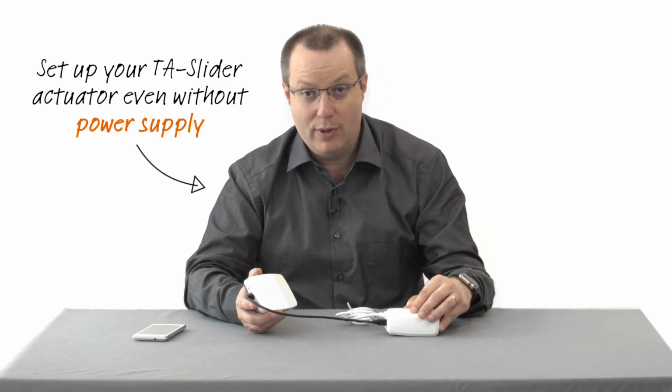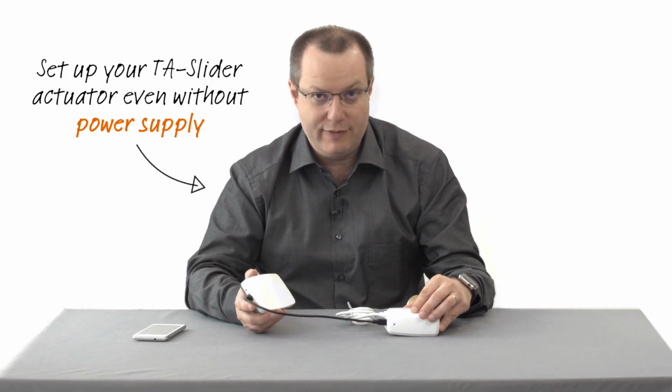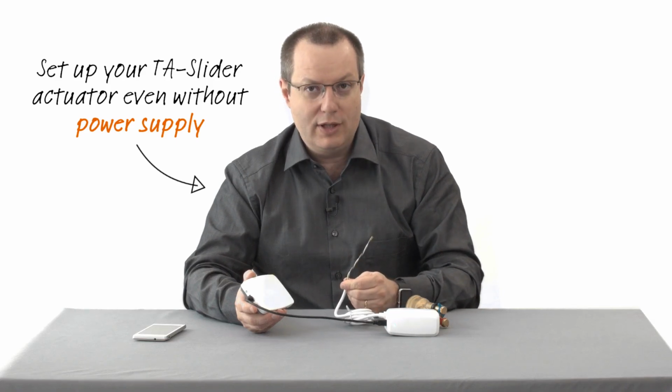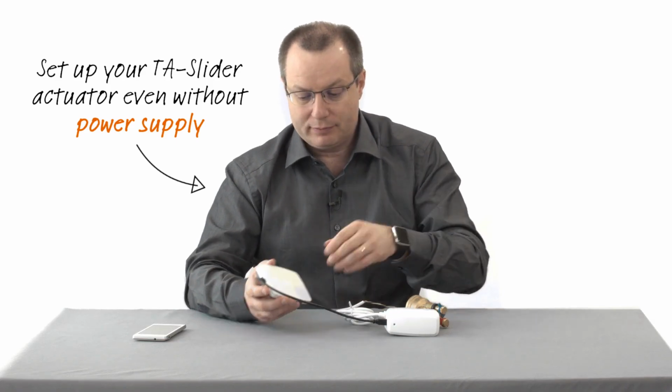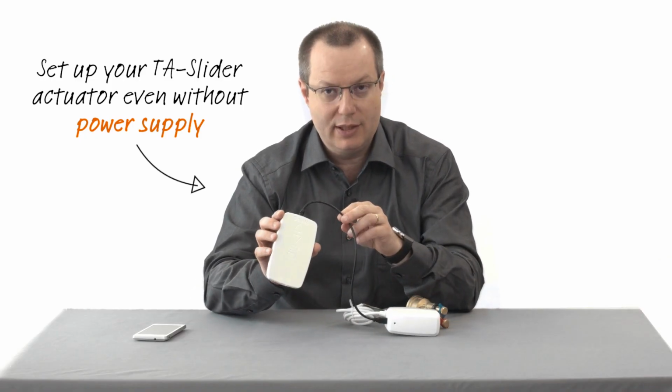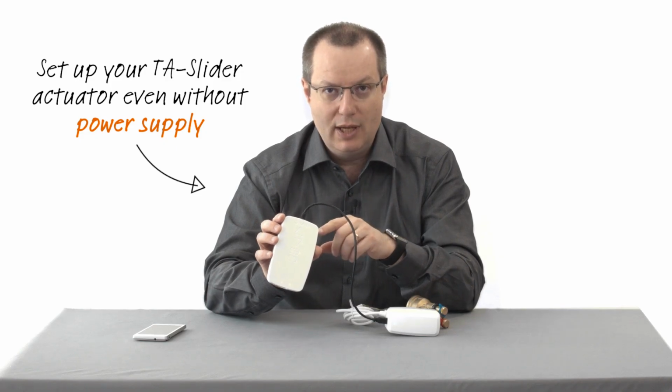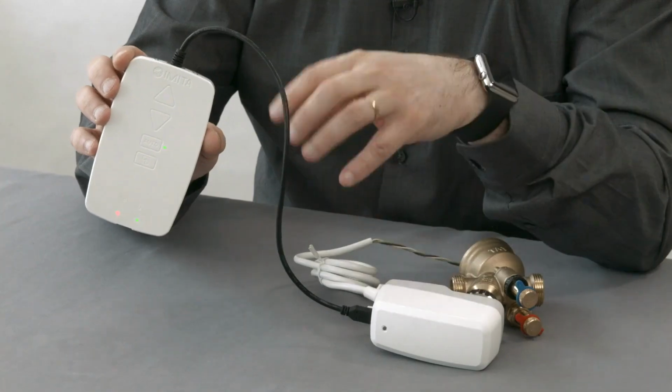One of the good features about having the TA-Dongle is that its battery is sized for powering up the slider 160 and TA slider 500, even though these actuators are not connected to the power supply. This means that by connecting the TA-Dongle to the actuator, you get an easy way to position it at a first position during commissioning time.